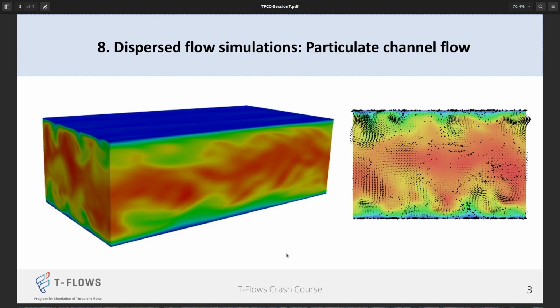And what will happen is that we need to advect the flow first, which is air or whatever the fluid that you need to advect, once it reaches a fully developed state. A fully developed flow in turbulence means that you have a statistically stationary turbulence. Let's say that the statistics of your turbulence are not affected by time anymore.